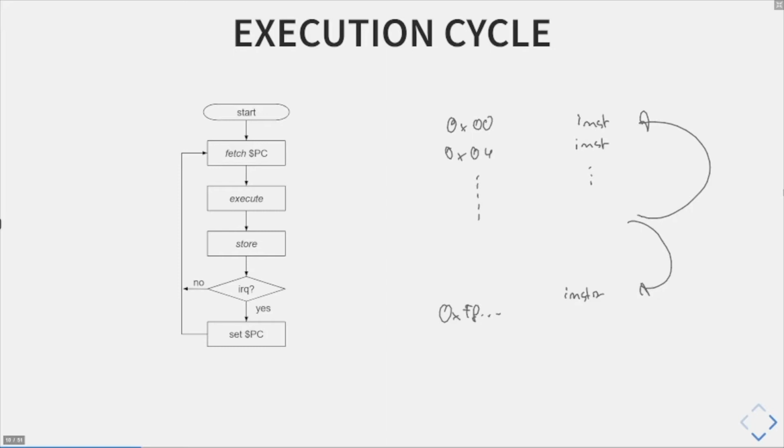What your CPU now does is what you see here on the left-hand side. You start your CPU or reset your CPU, which means you have a designated address in your CPU from which you start to execute instructions. This means you set the PC to this well-defined reset vector. This might be 0. So the effect of this is to set the program counter register to 0.